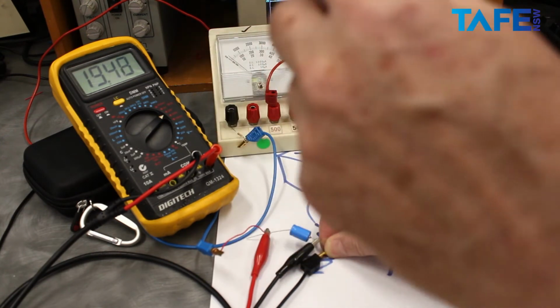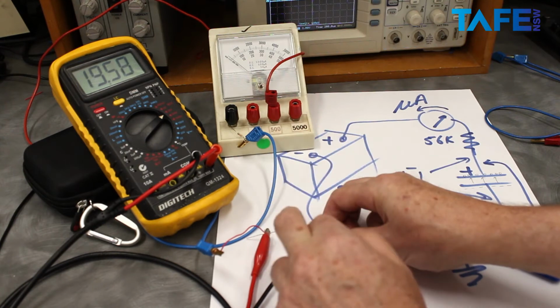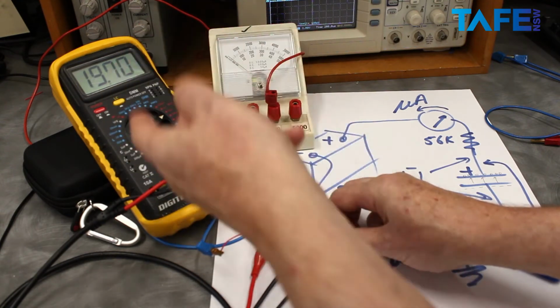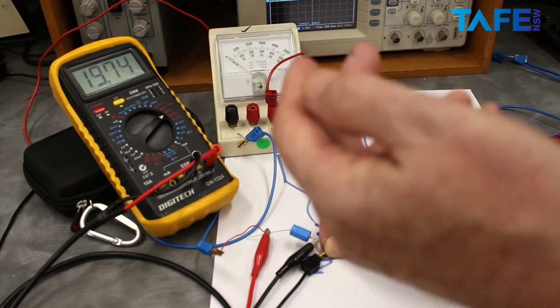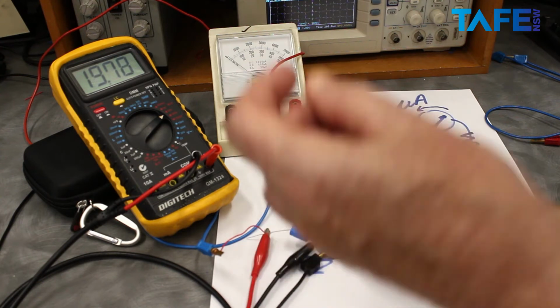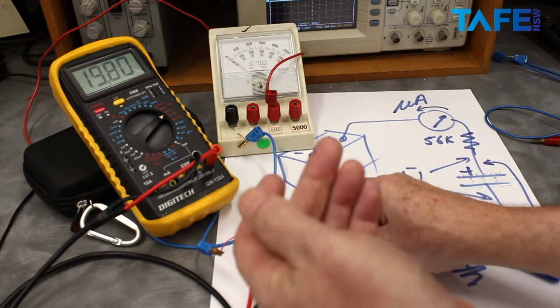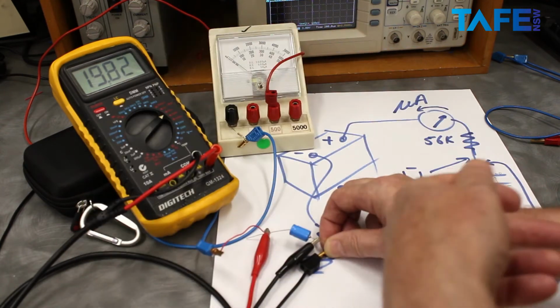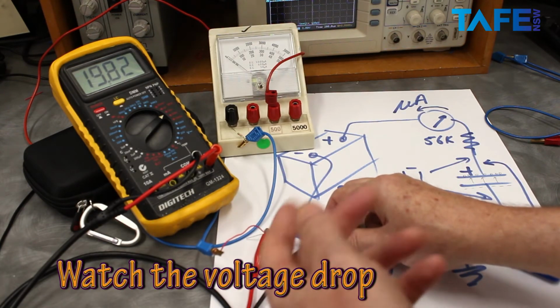We've got this equal voltage across the plates of the capacitor opposing the source voltage from the supply, and that's what gives us our V squared on 2. We have to use the average voltage in our equations to work out the energy in the capacitor because of the slow charge towards the end with that opposing voltage.